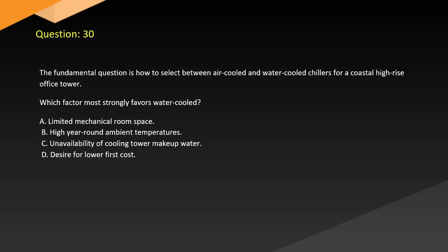Question 30. The fundamental question is how to select between air-cooled and water-cooled chillers for a coastal high-rise office tower. Which factor most strongly favors water-cooled? A. Limited mechanical room space. B. High year-round ambient temperatures. C. Unavailability of cooling tower makeup water. D. Desire for low first cost.